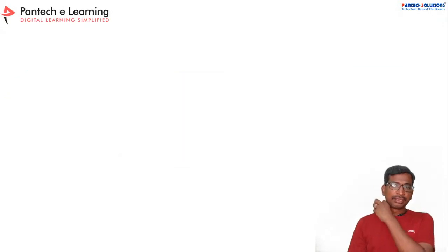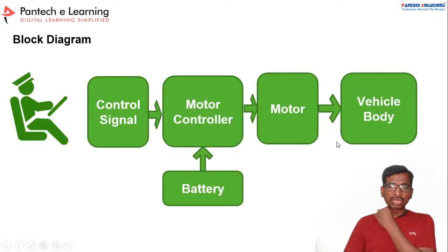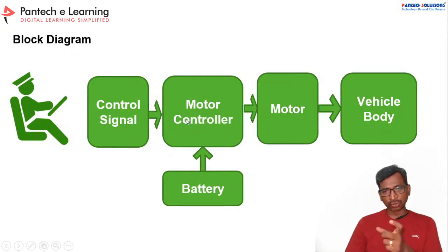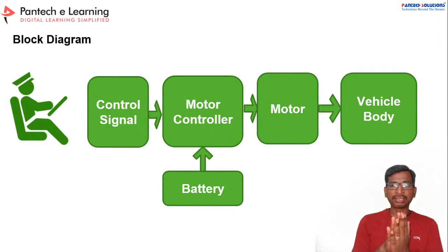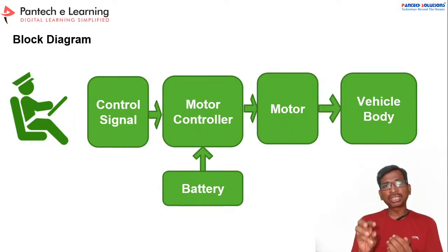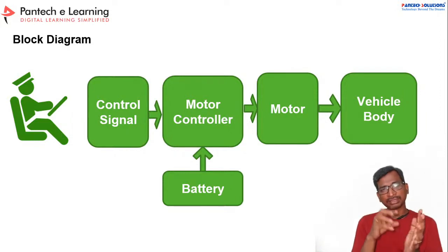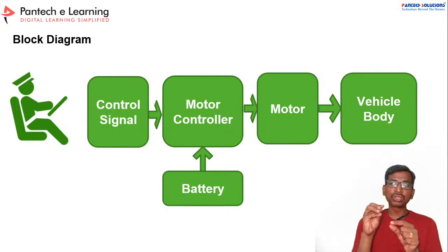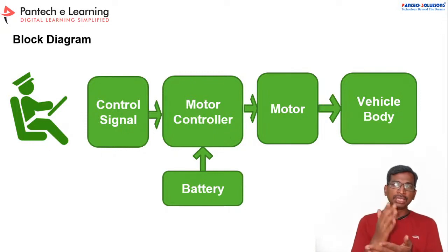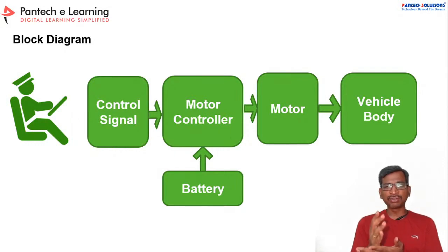And after the motor, we have to choose the right controller for the motor. Suppose if it is a DC motor, we have to keep one full bridge four-quadrant chopper. If it is an AC motor, we have to keep one inverter module. For the inverter module, the same topology is used for a BLDC, induction motor and PMSM motor. Whereas if you are going to use the switched reluctance motor, then you have to build your own converter, symmetrical or asymmetrical converter. Any one of the converters we have to develop as per the motor configuration.